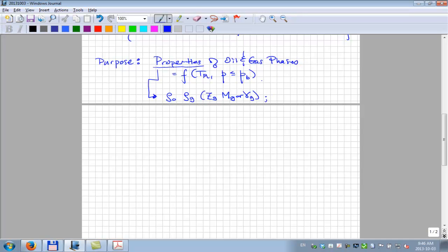We want to know the relative volumes, how much the oil shrinks. So we basically want to know the oil volume, and I'm going to call it shrinkage. How much does the oil shrink as gas comes out of solution, as a function of pressure?